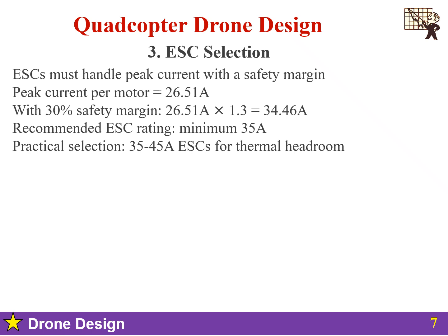Second, active thermal protection preventing catastrophic failure. Third, superior electromagnetic interference shielding. Fourth, firmware updates for performance optimization. Fifth, BEC, that is battery eliminator circuit, capable of powering multiple accessories. At this scale, ESC selection isn't just about current rating, it's about system integration and reliability engineering.